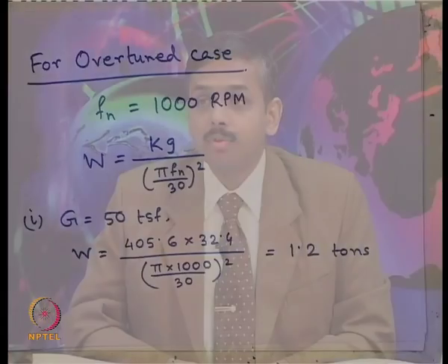After providing the foundation size, in this case it is far away from whatever we are providing. So, it is sometimes required to cross check whether really the no resonance criteria has been satisfied or not. Hence, to do that we have to recalculate back. So, another procedure is from the provided section you calculate back your Fn and check the ratio of F versus Fn. If it is far away from 1, we are on the safer side.